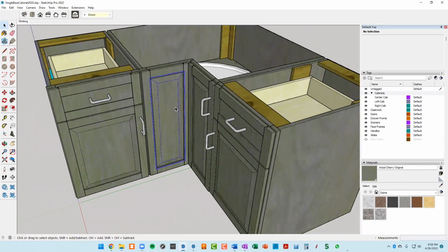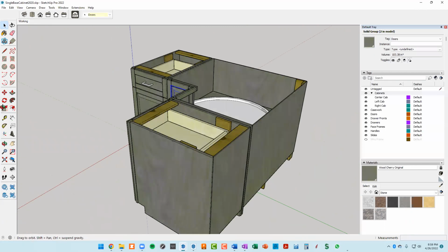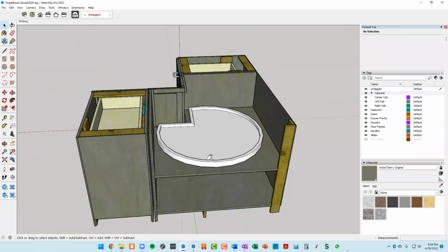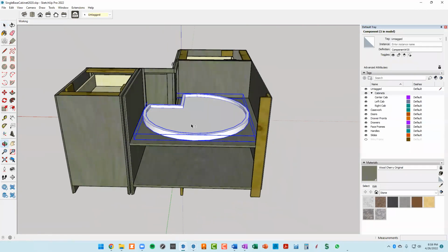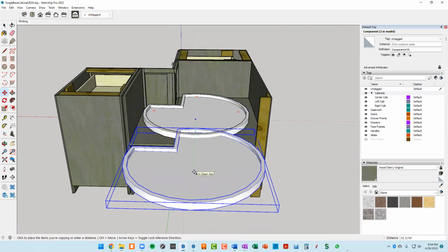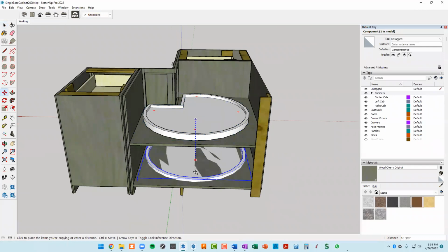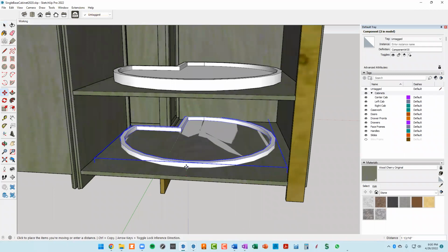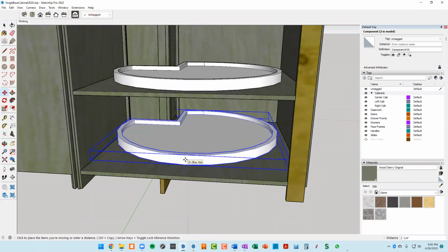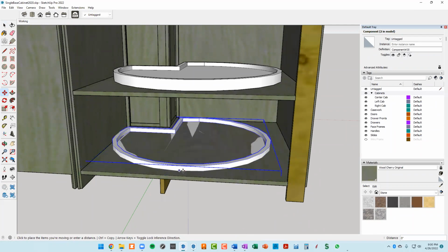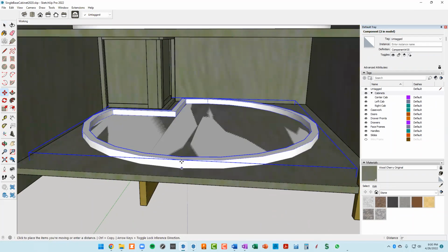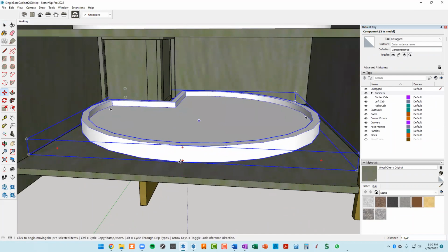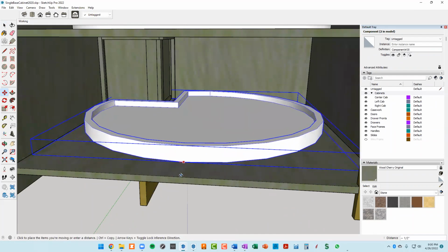You know, if you want one on the other, let's take a back. I'm going to hide one of these back pieces. I'll just copy this straight down. Hit my up arrow to establish my vertical direction. And that's in the right spot, except that I went down too far. So I'm just going to go straight up and then, oops, if I can get the bottom of this, I'll go straight up, click, then come straight down and inference off the bottom.